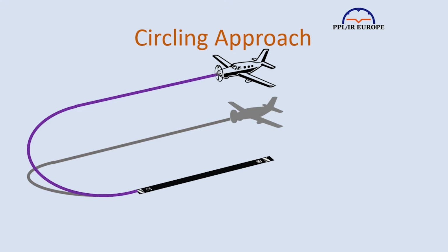Meaning that you should be turning to final as the descent is initiated. This also requires judgment, and my suggestion is to use constant aspect on a continuous turn onto the final approach, whether from downwind or some intermediate track if you're not doing a full reversal. Continuous aspect, which entails keeping a continuous slope, 3 degrees in IFR, is easy once you've grasped it, and you